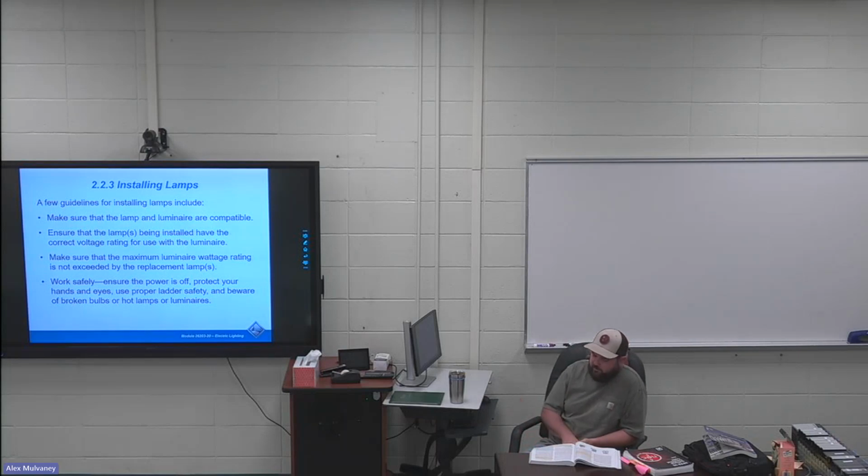So these ballasts can control what the frequency is, and you can get away from hearing that high-pitched hum. I don't know if you can hear it through the video, but there's a high-pitched hum in this room because they switched these fluorescent bulbs to LED bulbs, and you can hear the high-pitched hum. Still going.